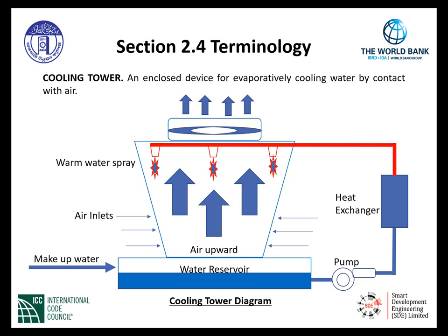This process evaporatively cools the water by contact with air. So the water finds its way back down into the water reservoir, and the process starts all over again by taking the water through the pump, through the heat exchanger, and up through the top into the nozzles.